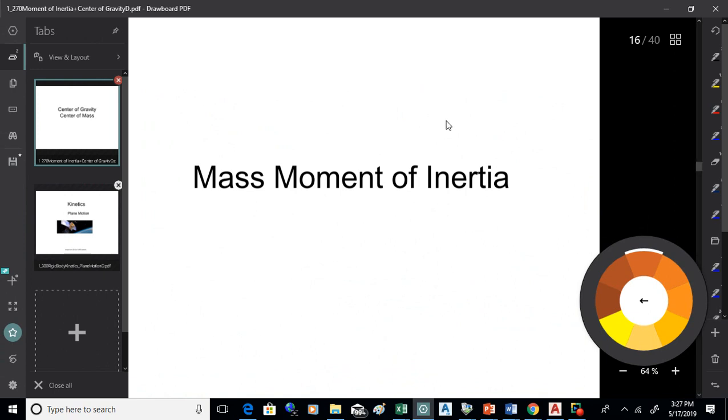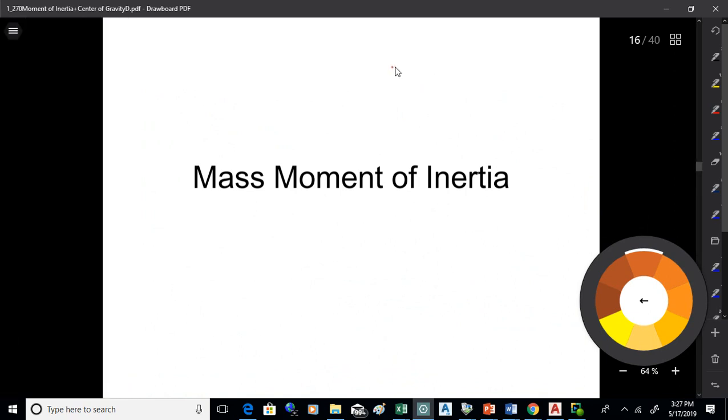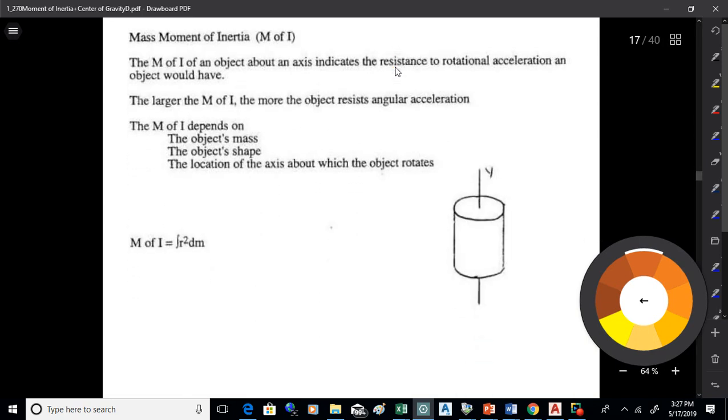All right, now another property that's quite a bit more abstract actually, is a mass moment of inertia. And that follows, it's on page 620. Okay. So I contrast this with an area moment of inertia. They're related things, but they're different. If you're taking strengths right now, and also in statics, you probably figured out how to calculate an area moment of inertia. That's for a cross-sectional area. It kind of relates to how an object flexes and bends when you load it up. This is a mass moment of inertia, and this is going to relate more to angular acceleration.